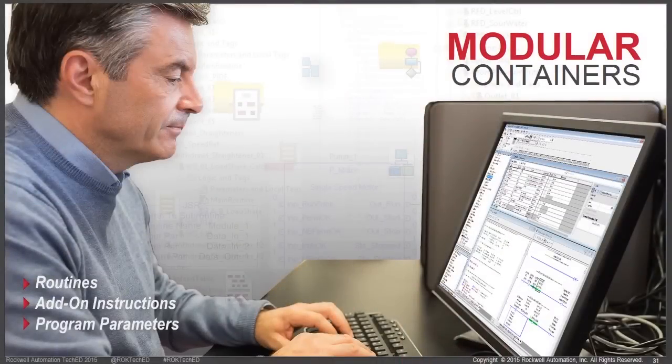Well, Miguel, the simple answer to that is yes, but let's dive into that a little bit. What you ask in your question is exactly why we are seeing the transition to more modular code designs today. Now, we not only see this in our hardware designs that the customers are doing, but we see this in their software designs too. Studio 5000 Logix Designer has multiple options for creating that modular code content that you're asking about. We have subroutines, we have add-on instructions, and our highest level container, the program.